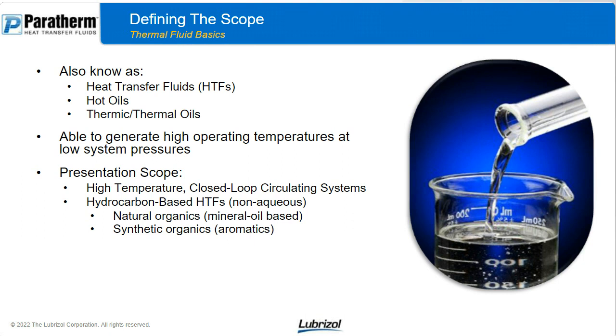With steam-fired systems or with direct heating, you might get a lot of high pressure points, you might have a lot of hot spots or localized overheating. And with thermal fluids, that technology was developed in order to create a more efficient, consistent operating temperature capability across the entire system without generating really high system pressures. High system pressures mean more maintenance. They mean more potential for safety issues. So whenever you have high pressures in a plant setting, those become the problems.